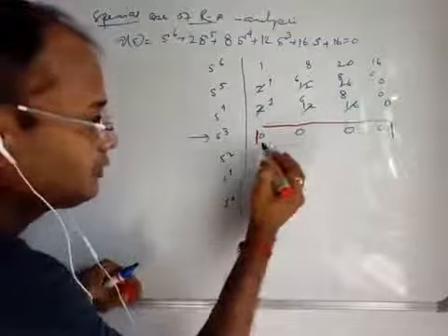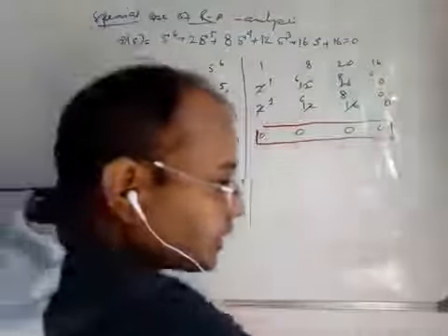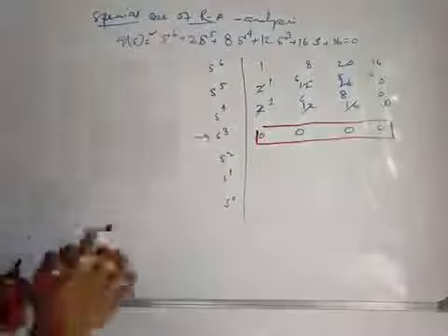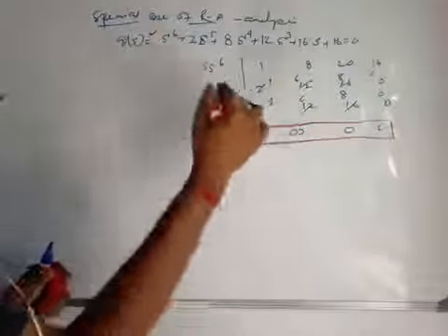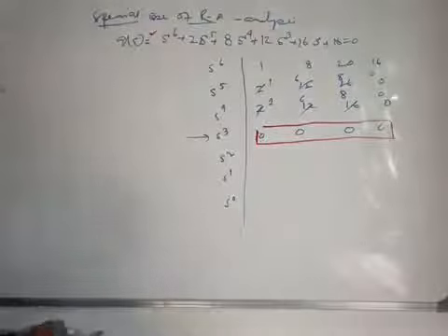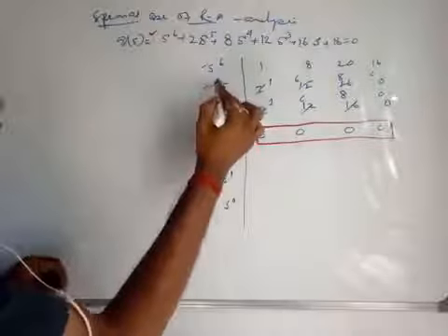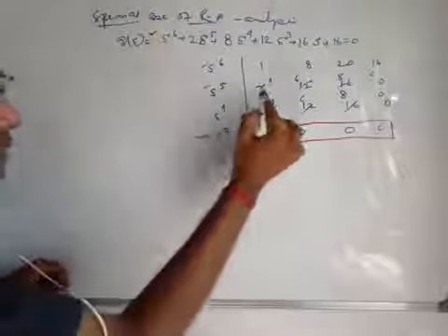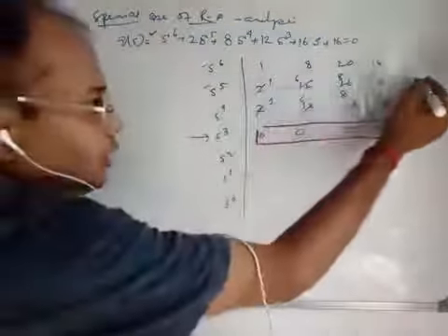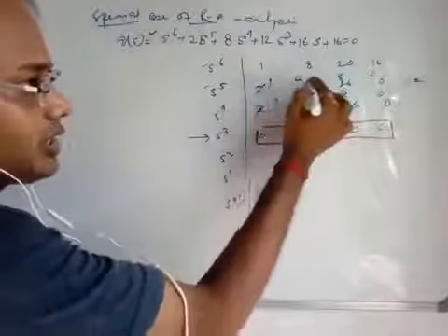Here we are taking a sixth order system, that is, a sixth order polynomial characteristic equation, and we have formed this Routh array like this. The similar procedure we have already discussed. Now s to the power 6, s to the power 5 and so on. And see, this is 2, 12, 69, 0. So we may just divide all the elements by 2 and you get 1 6 8 0.